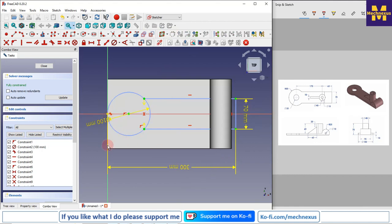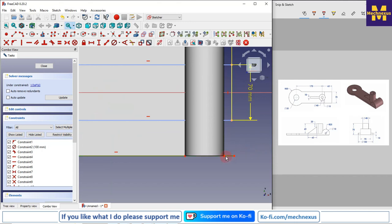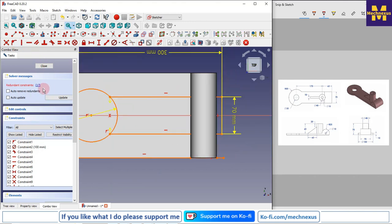Now I will draw my closed profile and then I will mirror it. For this I will convert the edge, because I would require this edge to close my profile. So first I will close this one, I will take the outside, and here I will make the coincident constraint.